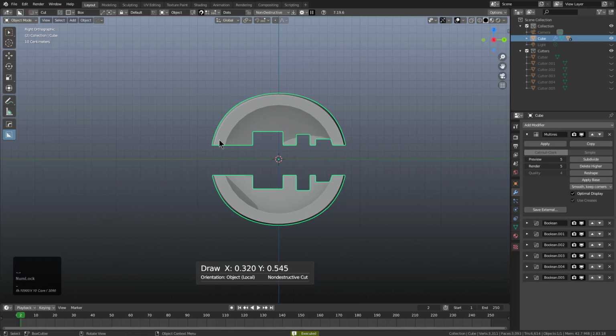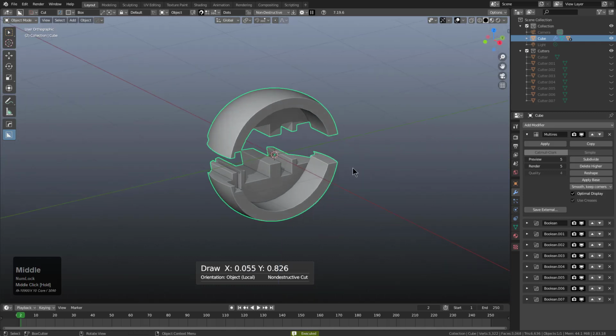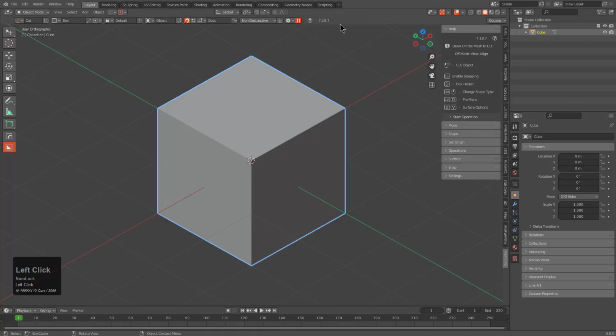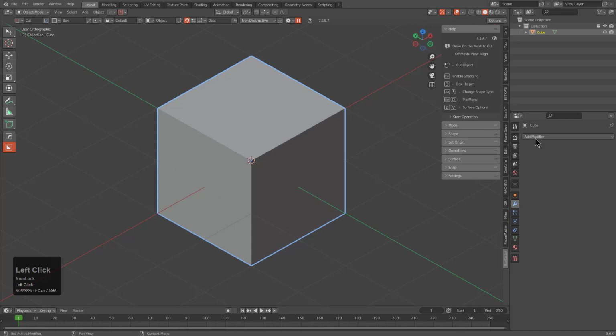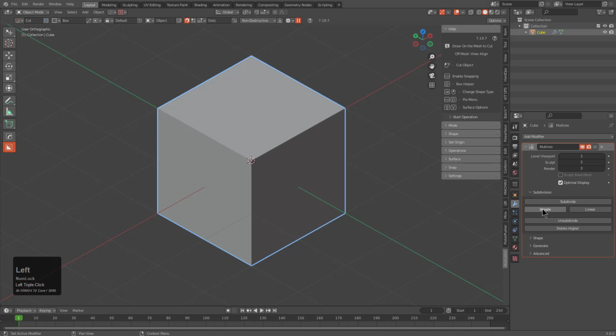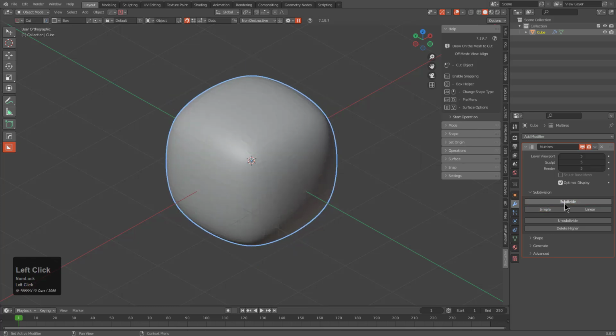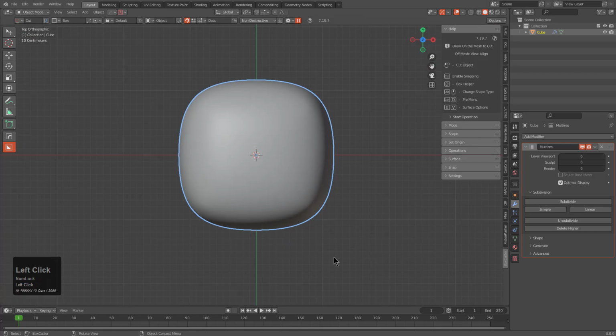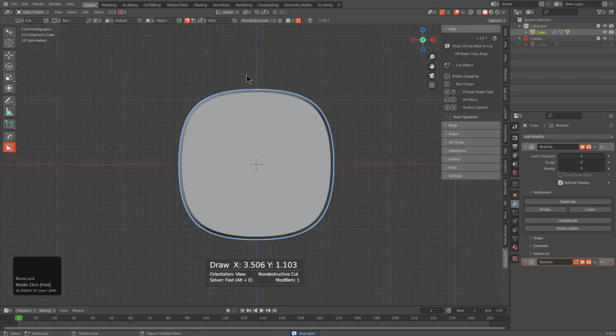However, this is no way to work because it simply is going to cause issues down the road, disabling two of the most important systems inside of Boxcutter. So for that reason, some improvements have been had with this latest version 719.7, and so let's just show it now. So we'll go in, add multi-resolution, hit subdivide a couple of times, and then from here just begin performing our cuts.